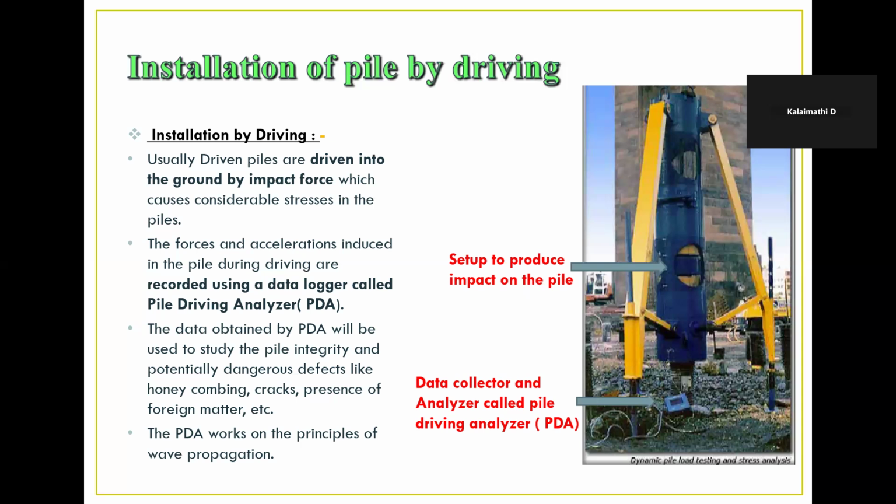The data obtained by PDA will be used to study the pile integrity and potentially dangerous defects like honeycombing, cracks, presence of foreign matter, etc. The PDA works on the principle of wave propagation.